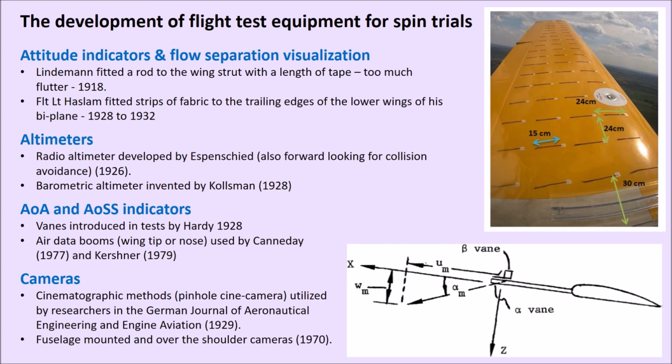Something that I've used in the past for flight test research programs is an SBG Systems AHRS, attitude, heading and reference system. As I say, I've used that before. Weighs I think just under 40 grams, but can provide 3D attitude and acceleration data during dynamic maneuvers such as the spin. So that's just an example of how technology is pushing this field of research forwards, and how more and more accurate and faster frequency data, for example, is capable now than ever before.